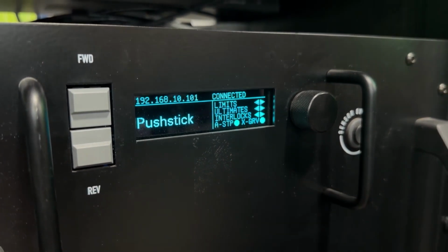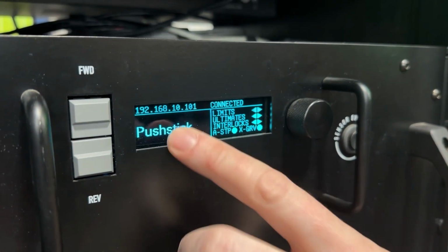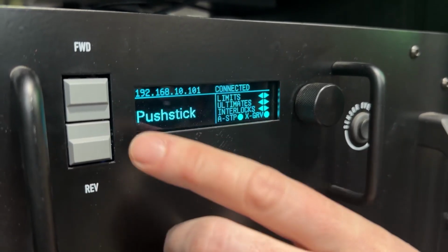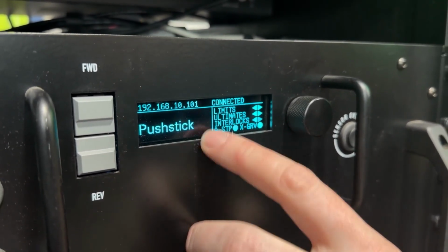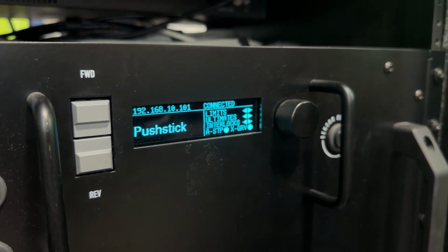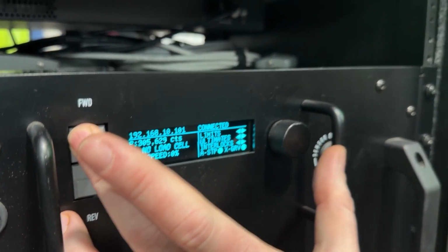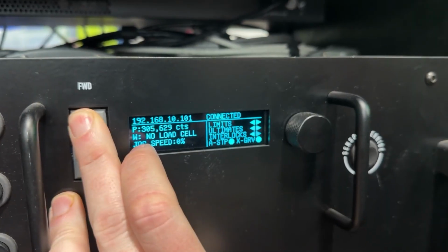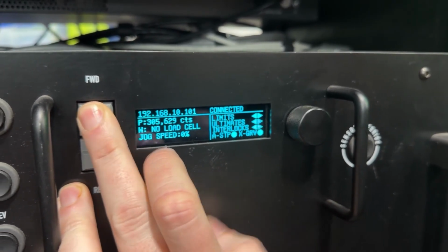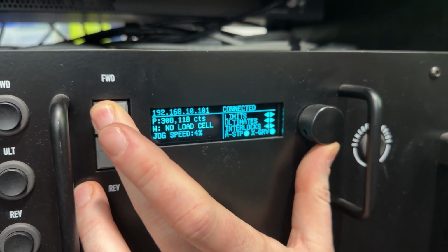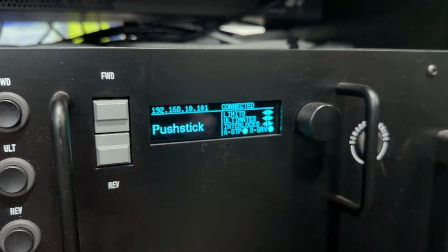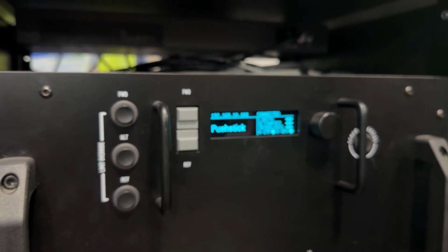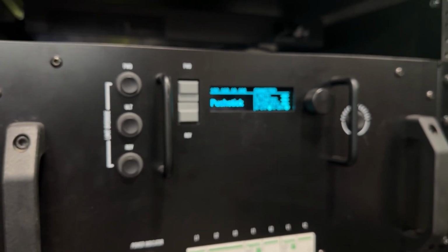And then you get the axis's name and its IP address and its connection status. If you start to see other faults, drive faults, things like that, you'll get a scrolling list here. The name will go away and you'll start to get some of the feedback there. You get live ability to jog, so you can see the encoder counts, and if it has a load cell, you'll see the weight, and then you'll see what our current jog percentage is. And you'll see as we're counting. So as you're installing, commissioning, troubleshooting, any of those things, right from the stagehand's faceplate, you can get all that information and feedback to know if things are working as intended.